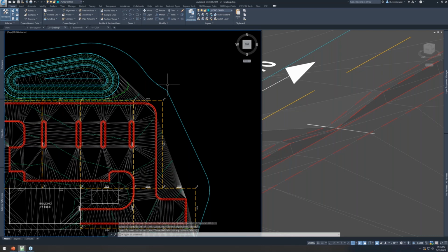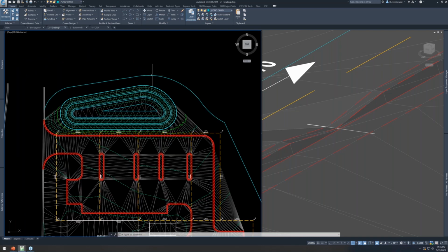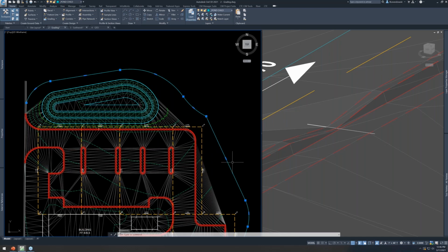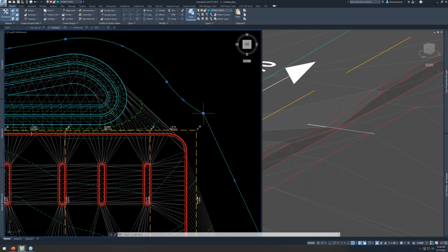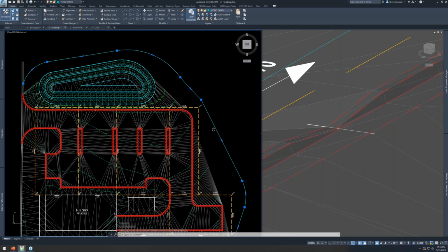Now, there's a couple ways to do this. If we're trying to force a berm, give it some elevations, and then use AutoGrader to daylight to existing ground. We could also just pull elevations from existing and dump that into the surface. It depends on what you're after. But I want to show you one other grading family type in here, which is the daylight to surface or target to existing surface option.